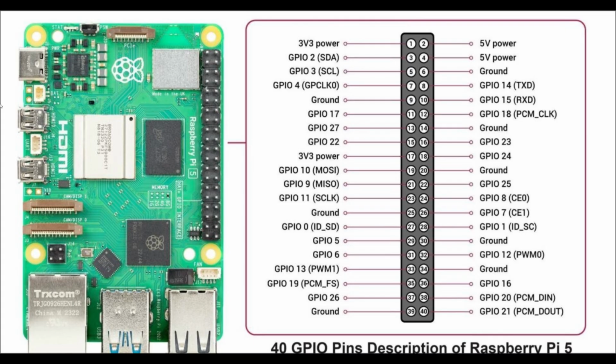The buzzer is used to alert the driver when dangerous behavior is detected. One wire connects to the GPIO pin, another connects to GND, which is ground. Always make sure the voltage matches the buzzer's requirements. Raspberry Pi GPIO pins output 3.3 volts, not 5 volts.